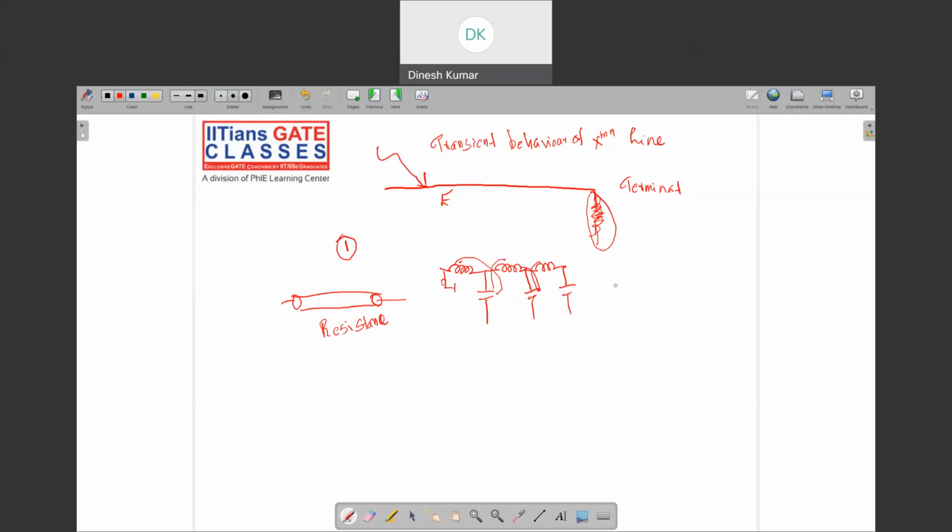Okay, so that is basically something known as surge impedance. That is root of L by C, inductance per unit length divided by capacitance per unit length. So this almost remains a constant for each and every transmission line. For most transmission line cables it is nearly 50 ohms. That's how we actually design it: 50, 60, 120, like that. So this is very important.